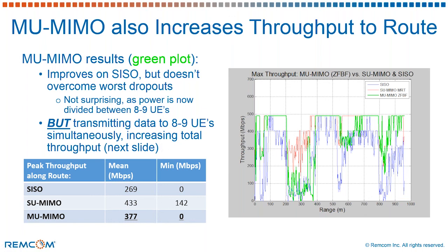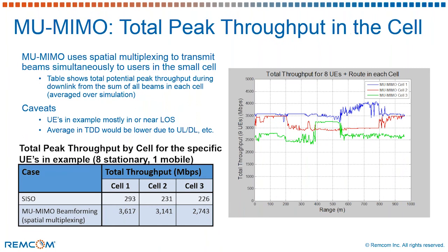Next, we looked at diffuse scattering, and as we mentioned earlier, diffuse scattering impacts the propagation in a couple of different ways. First, it scatters waves in different directions than traditional propagation and reflections would scatter. And second, it depolarizes the signal. So when we're looking at multiple antennas and perhaps trying to transmit multiple beams, there's a chance that there's some cross-polarization terms between the different antennas that could have either a beneficial or a negative effect on the propagation and the beamforming.